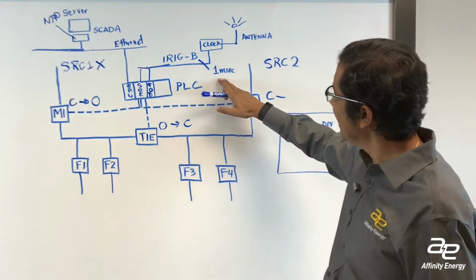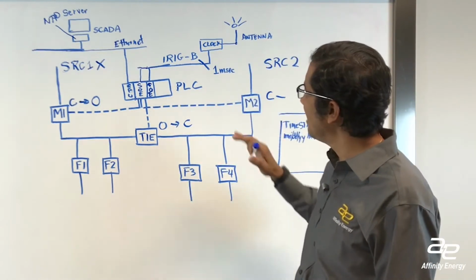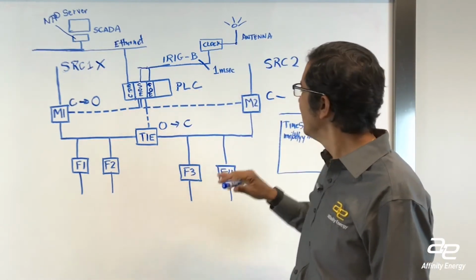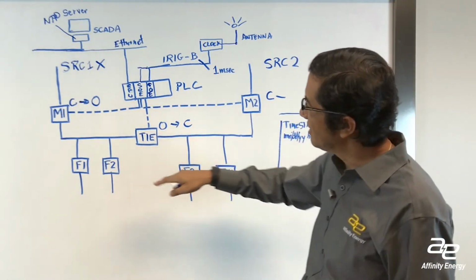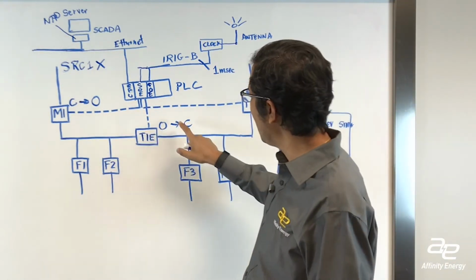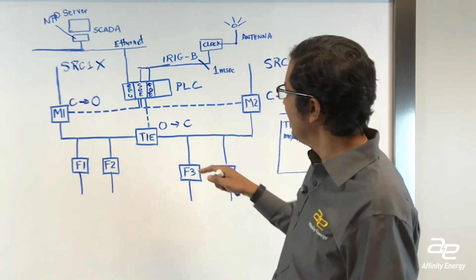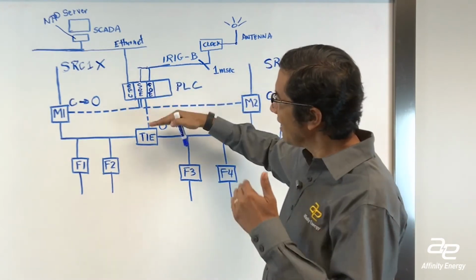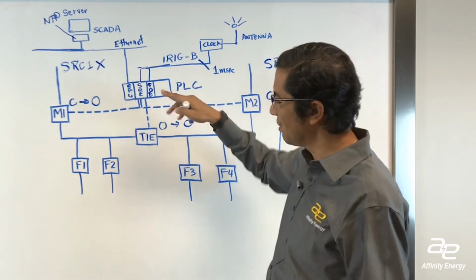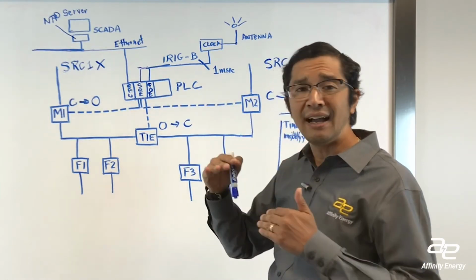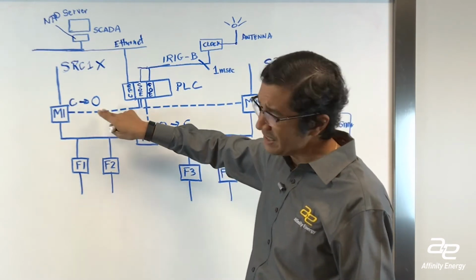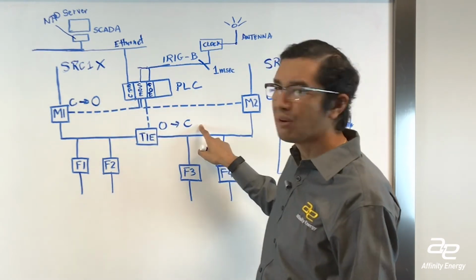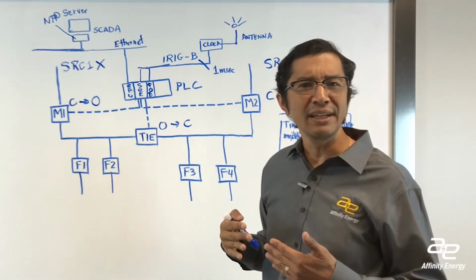Having a 1 millisecond time resolution that you can count on is going to ensure that when you go to look at, okay, did this one open before that one closed? If the clocks on these and the internal mechanisms were off by several milliseconds, you may not actually be able to definitively tell whether this occurred before that occurred, because your time base would be incorrect.